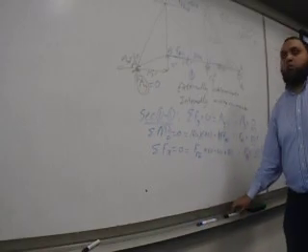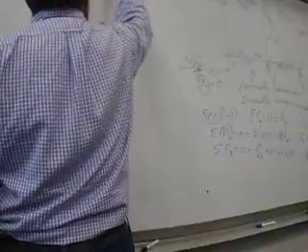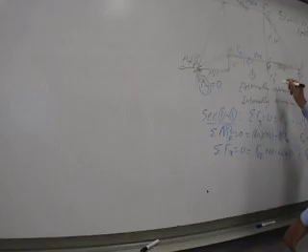Now, can you go back? We can go back to our full structure and solve the thing globally. If I go back, I'm now using the black one. If I go back here and solve everything, and I take a moment at A, sigma moment, or rather, sorry, I'll take a moment at D, sigma moment about D equals 0. I know this one, but my unknown was Cy. So sigma moment at D equals 0, so this is equal to 15 times Cy.